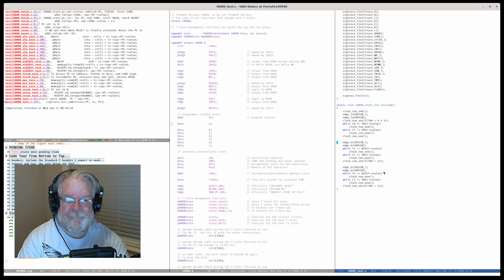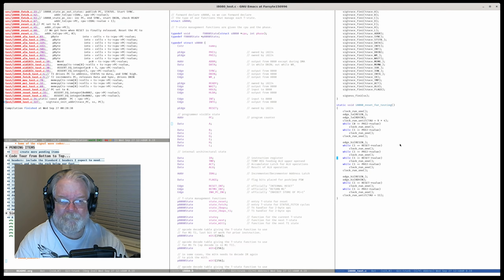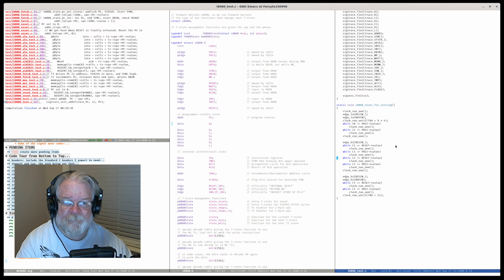Let's move reset first. So what I'm going to do is I will go to just before the beginning of the cycle, then I'll hit reset. And I'm going to do this twice more. Give reset a bit of time to move. And actually, I believe reset, by definition, has to be there for 3 cycles. So let's split the difference.